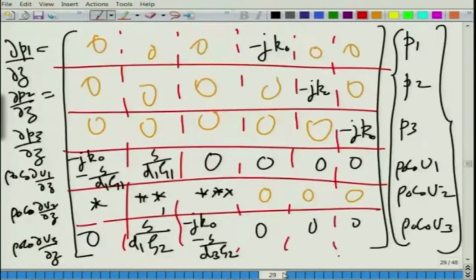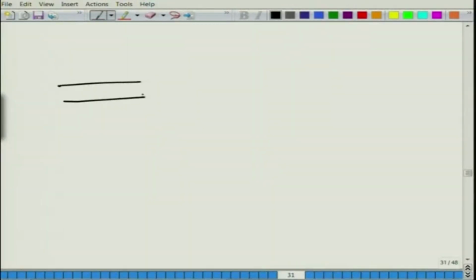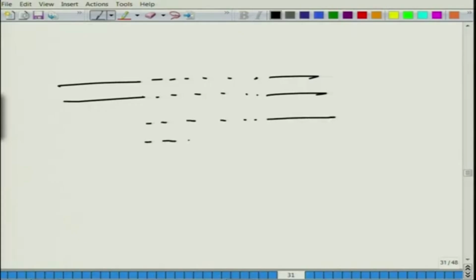Now, coming back to the problem, we are left with integrating this particular matrix, and to this end we will have to go to MATLAB and integrate it, with the understanding that we also have to apply appropriate boundary conditions. So, before we go to MATLAB, let us write down the different boundary conditions that we have. Basically, for ducts of this sort, called a cross flow expansion duct, as you know, it is an expansion kind of thing.